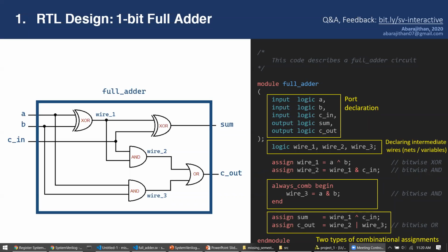Because of that, in SystemVerilog, what they have done is they have removed all that. It's still there, but instead they have added some new things called always comb, always ff, and always latch, and we will look at those later. The idea is that we use these things for particular purposes. Comb is used for combinational, ff is used for flip flops, for registers, latch is used for latches if you want. But latches are generally bad. If you want a latch, you can use that. So that is the difference with always at. In SystemVerilog, you don't have to use always at all. Avoid it if you can, but if you want, you can still use it.